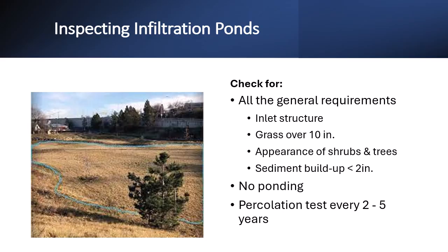Infiltration ponds must also have a percolation test every 2 to 5 years to ensure the water continues infiltrating at a rate that will not cause problems such as flooding. If you're unsure when the last percolation test was done, schedule one and then maintain the test schedule.